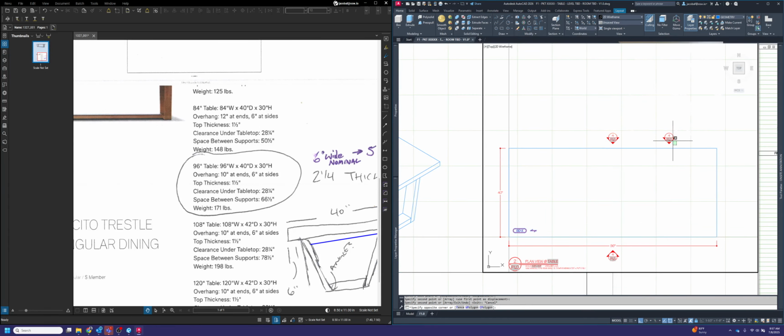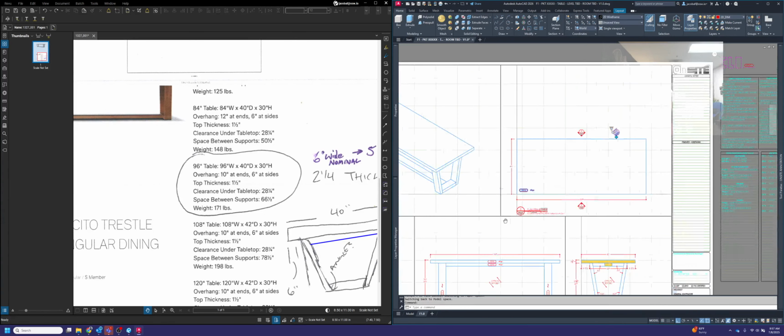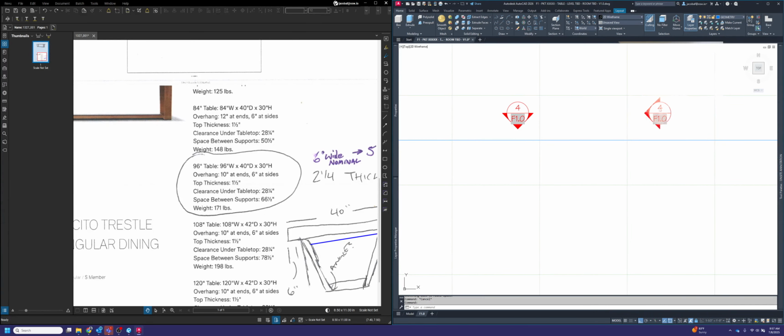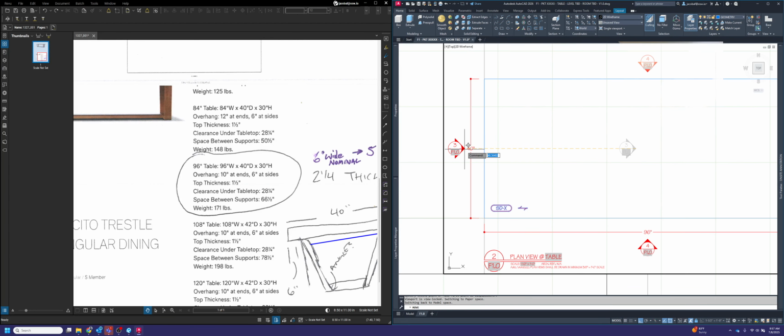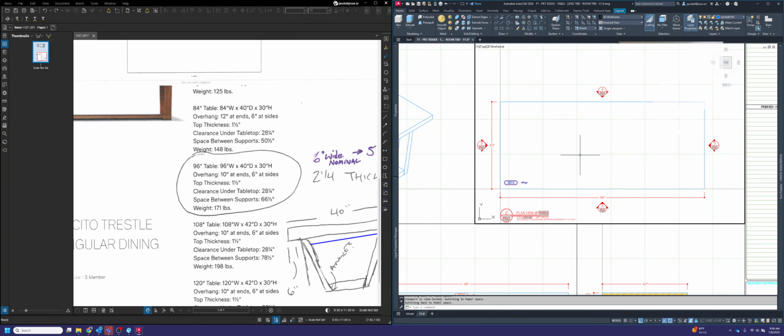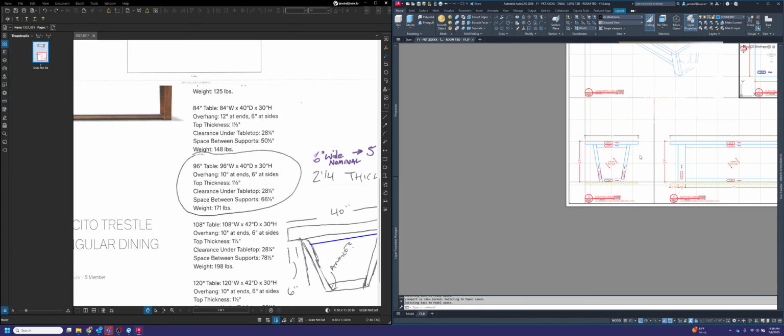All right, moving on. Let's do the two sides. Sides are view 3. So back up to your elevator or your plan view. Mark those as 3 on F1.0. And we're going to place those on the drawing. Again, I'm offsetting these all the same distance, so 2 inches off of the view. 3, 3, 4, 4.